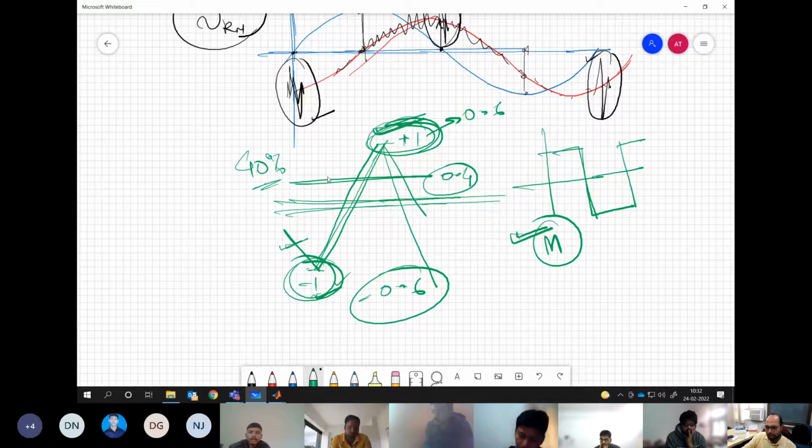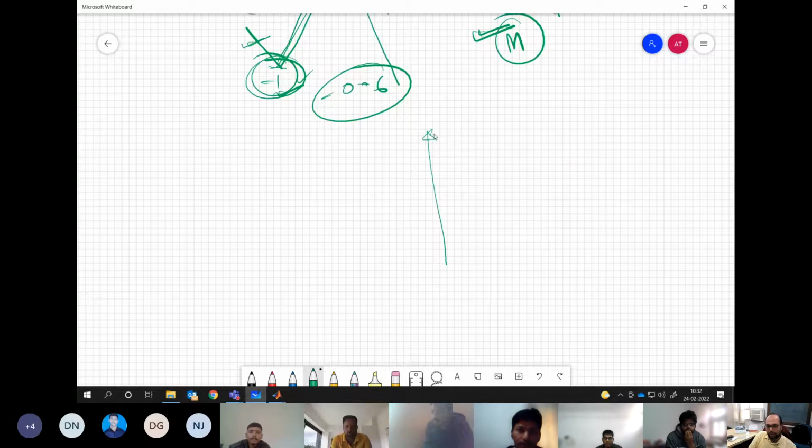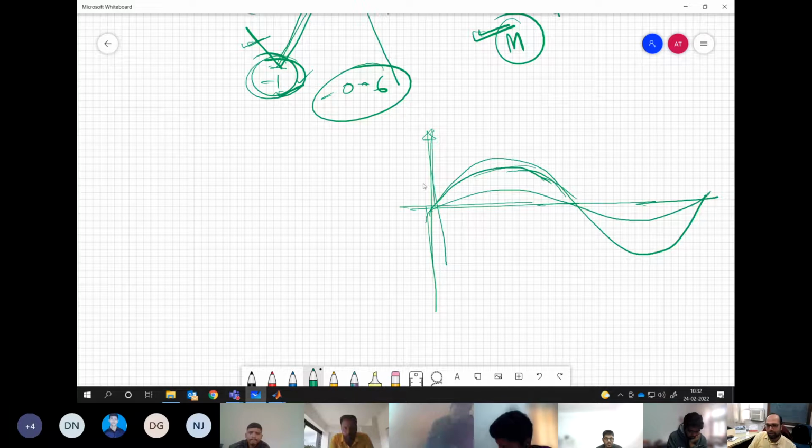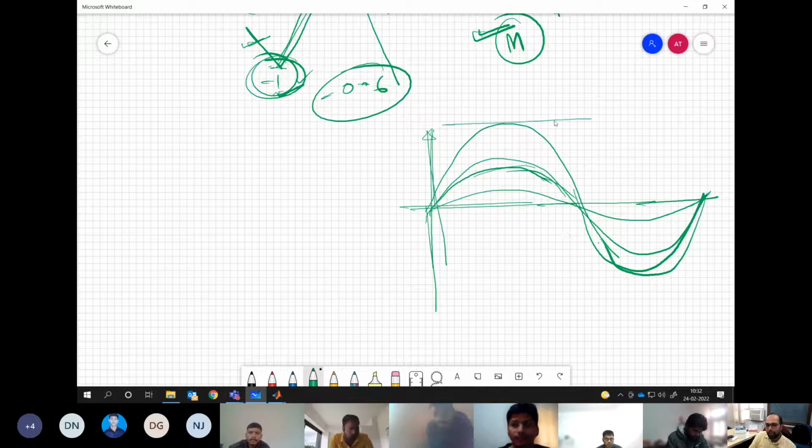Meaning is that you are having a motor to control. So for motor control, you will have V by F by default in most of the cases. You have a sinusoidal modulating signal. Now, it is not necessary that this sinusoidal component will always have the same peak value. It will be somewhere here, sometimes somewhere here. Frequency will also change. But whatever we are doing, we are keeping it within the boundary. What is the boundary? +1 and -1. This is our carrier boundary.